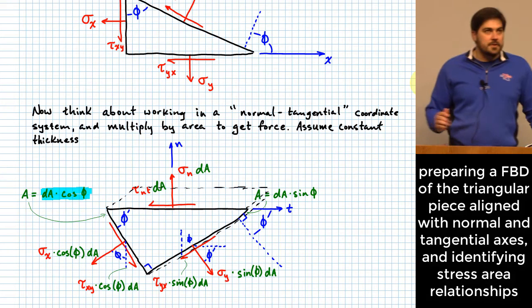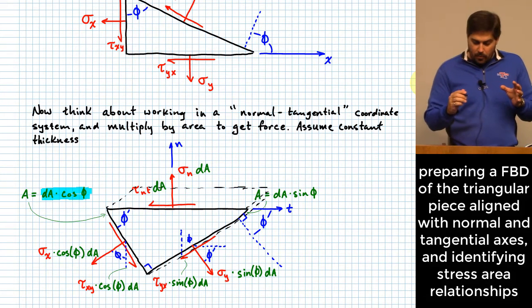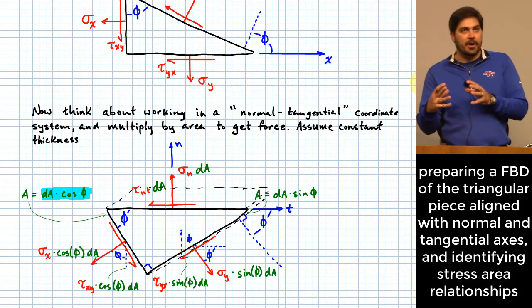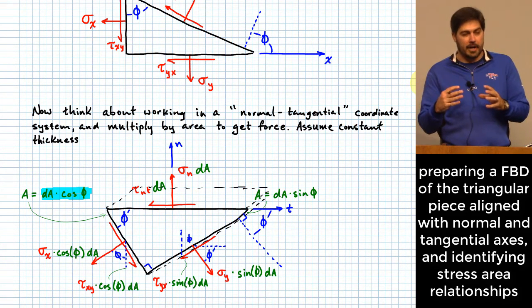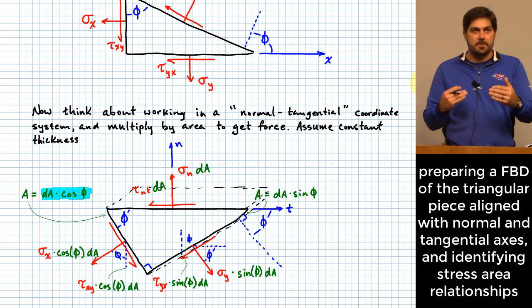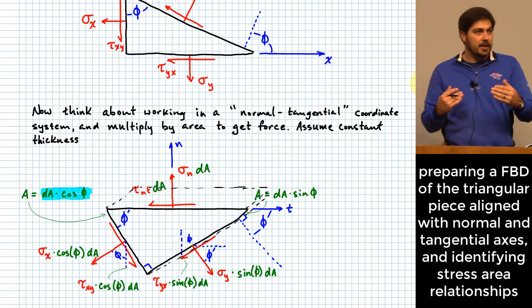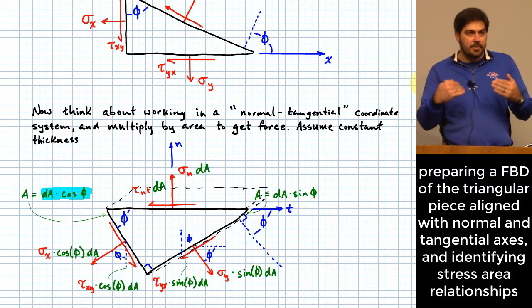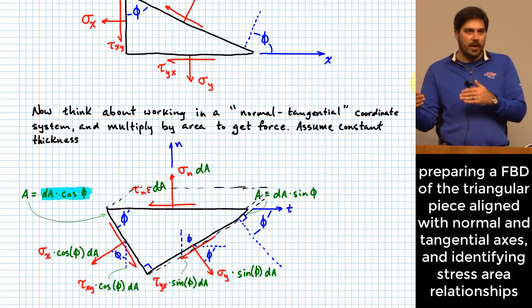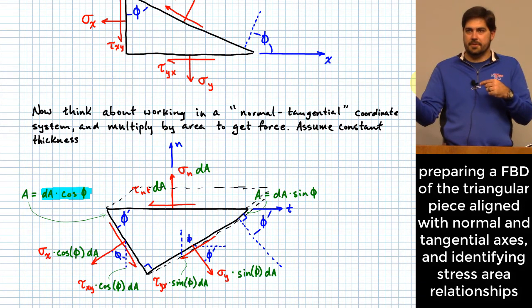We're talking about stresses, and in order for us to use a free body diagram method, can we do that in terms of stress? Okay, free body diagrams, typically we converse in what kind of unit? Forces, right? So we need to transform what were stresses on this free body diagram into forces instead of stresses. Well, how do you go to force from stress? You have to multiply by area, okay?